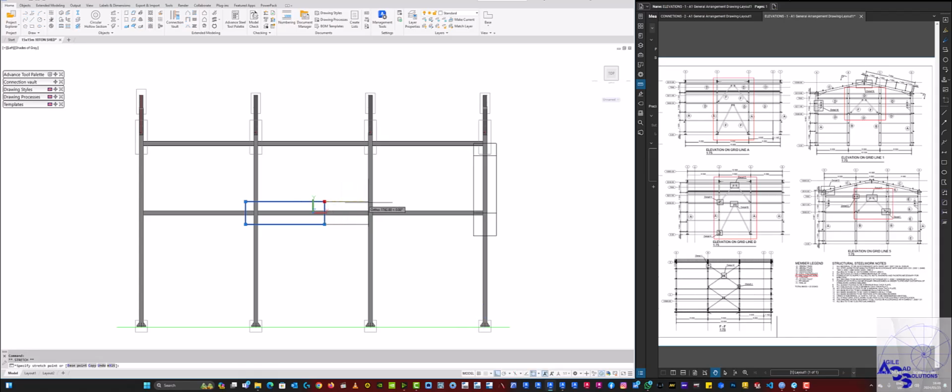Select the node as well, click the node to the side. Select the node, click the node up just above this tie beam, because our bracing is going to be connected to this tie beam and this level as well. So let's do the same. We go downwards. All right.